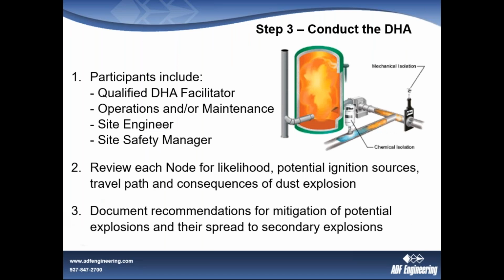Then you conduct your DHA, including such participants as the site safety manager, site engineer, operations, people who are familiar with the site and the way operations looks at all periods of time. You may find that 99% of the time you don't have dust clouds in the room, but the operators or the people who are doing the cleaning, they recognize that under certain conditions, a dust cloud can be generated. So that needs to be pointed out.